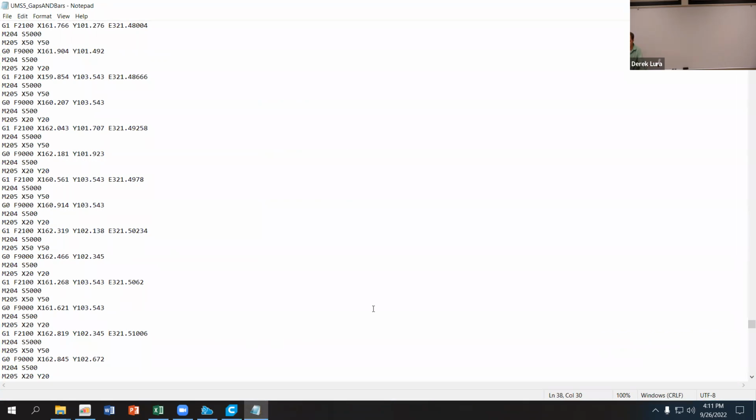But there's nothing magical about this, right? Like it's just, go to a new position, extrude a certain amount, go to a new position, extrude a certain amount. And I think hopefully you guys can see that if I knew the geometry of the part, you could by hand write out the code you needed to print that part. And, I think if you go back historically to CNC machining, this is a transition from manual to CNC to layers upon CNC machining.